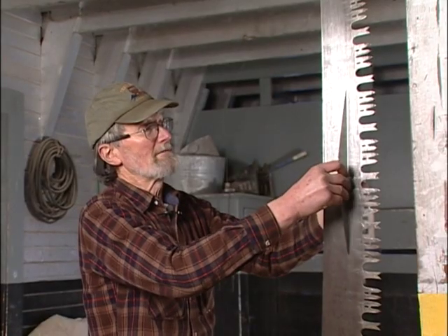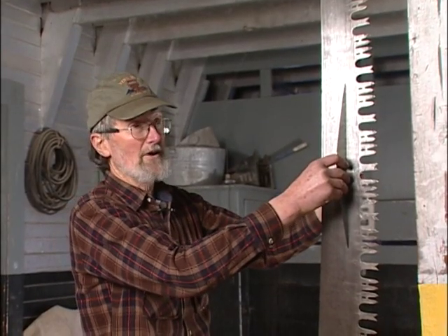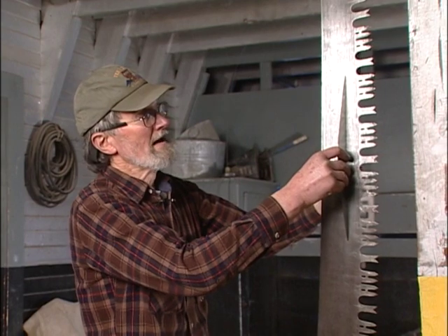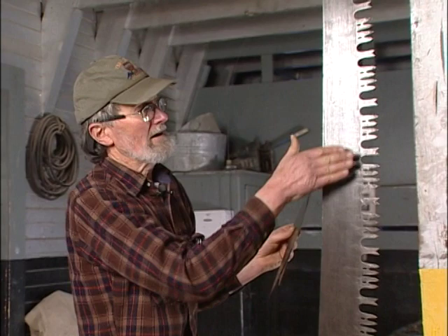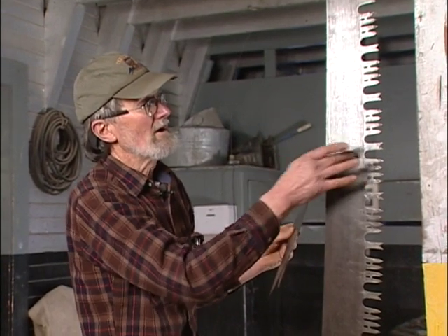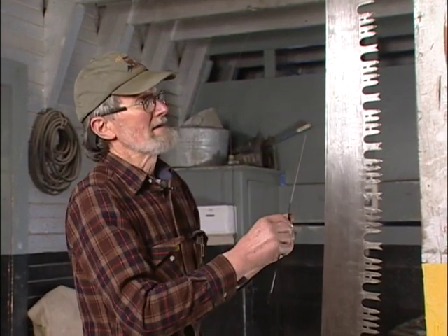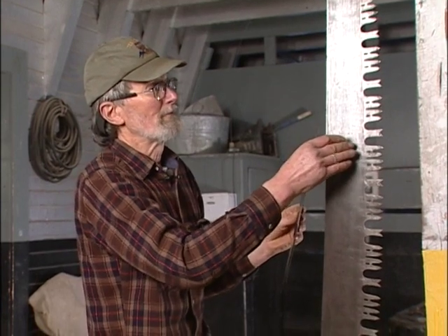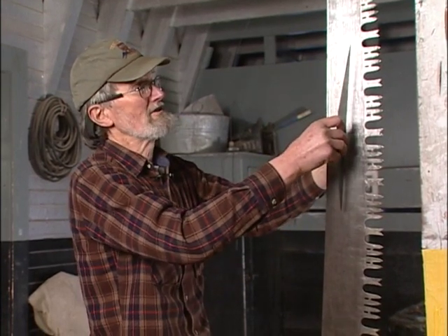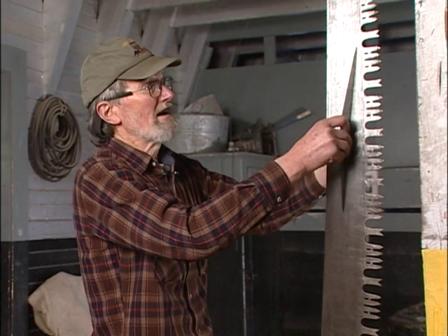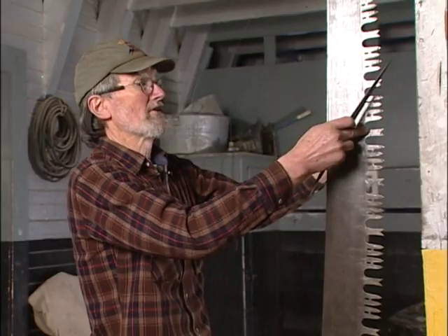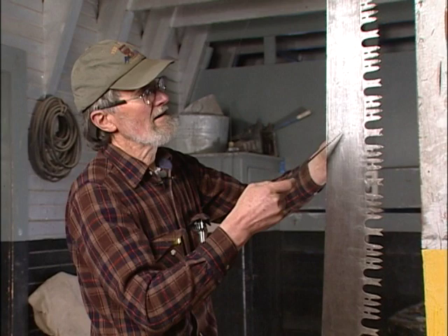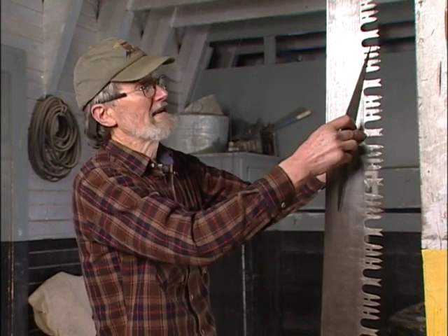Now, once I've located a bump, what I need to do is figure out what its orientation is. By that I mean, does the kink or bump go straight across the saw, or is it at an angle? Because if I just place the straight edge on the saw in one place, the natural inclination would be to say, okay, I've got a bump here and it goes straight across right underneath this raker, but in fact it may go off at an angle.